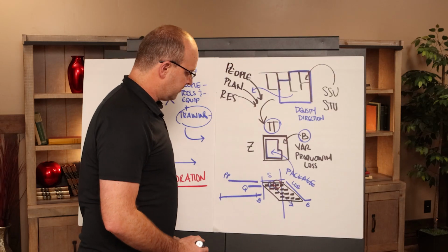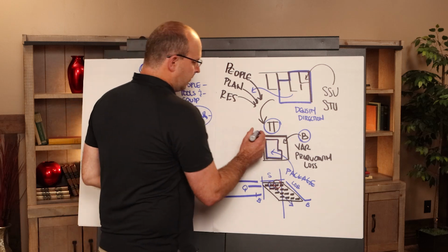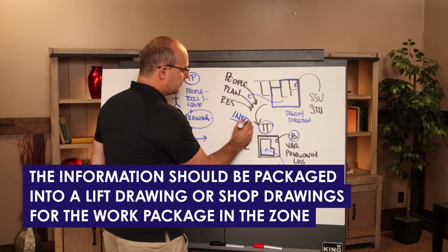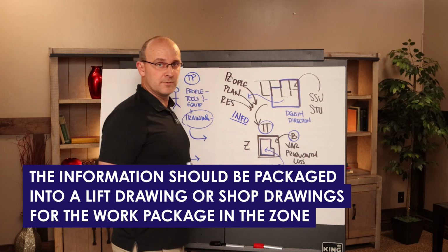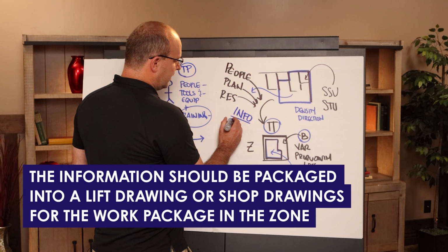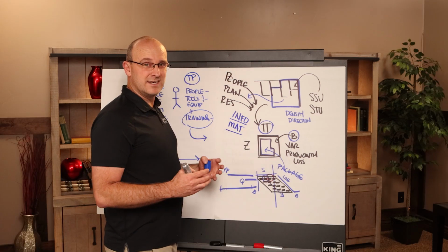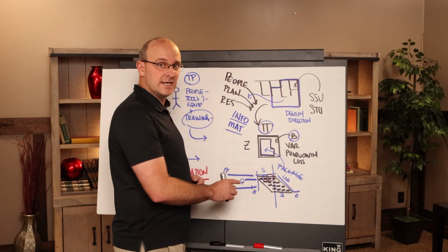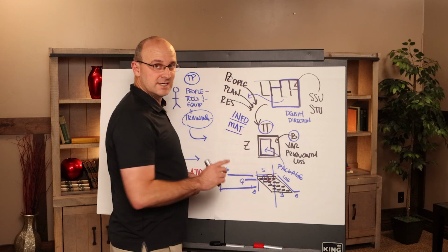So this is the brilliant concept that I want to talk to you about now: when you get to that zone, the information should be packaged into a lift drawing or shop drawings for that work package in that zone. When you go over here and you open up your materials, those materials should be kitted or prefabricated in a manner that they can show up pre-staged, ready to that zone for that work package in that takt time.